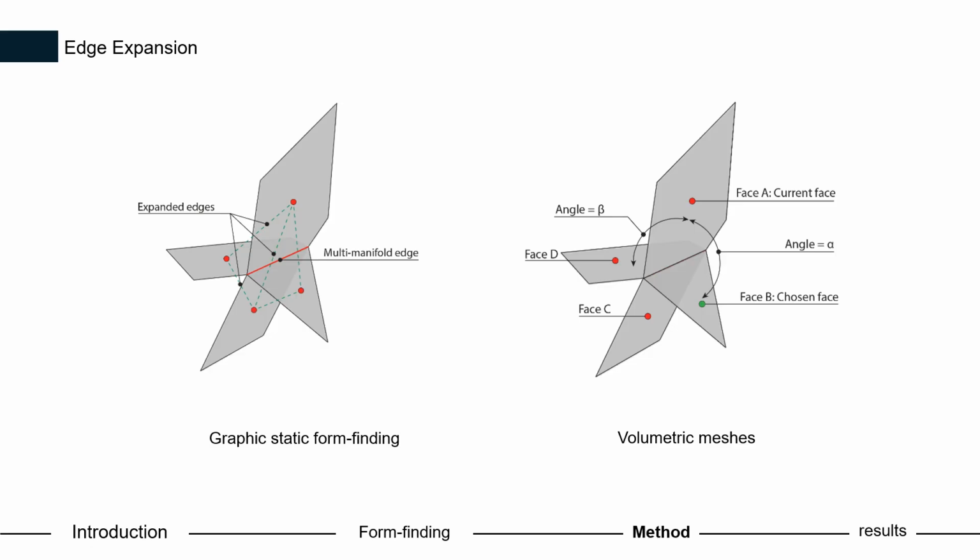Before we segment, we resolve multi-manifold edges. These are edges shared by more than two faces, which most graph algorithms cannot handle. We apply edge expansion. For each multi-face shared edge, we create pairwise connections between every incident face in the dual graph, tagging these as expanded edges. This converts an ambiguous many-to-many junction into a set of simple two-face links, so weights and clustering behave consistently.